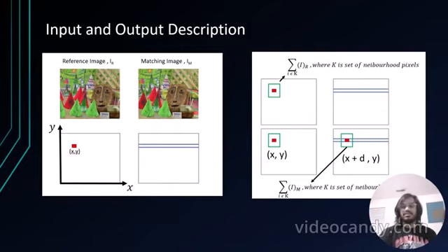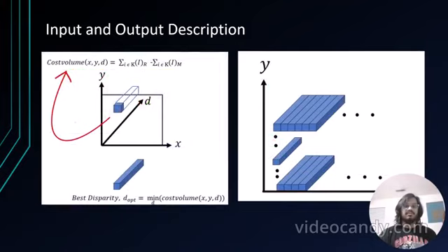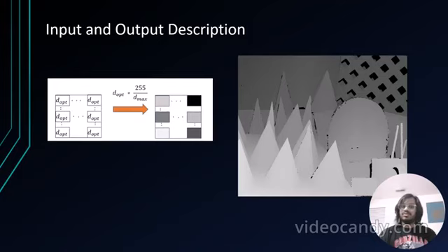So a traditional approach would be to use a sliding window, as seen in this diagram. You would calculate a cost volume, which all methods do, and aggregate over all the pixels in the image. Finally, use an optimization to get disparity values once you solve the cost and convert those into grayscale values where lighter shades represent objects which are closer to the camera and darker shades represent objects that are further away from the camera, as you can see on the right here. You can also use a heat map. This is one of the many representations for depth.